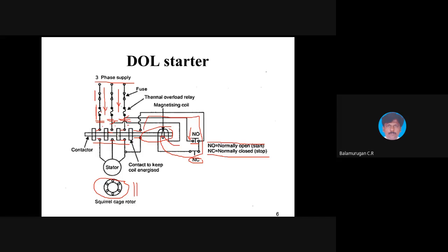And here you have to remember the condition. We are not reducing any voltage here; we are applying the full voltage. So these two currents will be almost the same, and we will not have any ratio. So the starting current will be equal to the short circuit current. This is the final equation for the DOL starter, the ratio between the starting torque and full load torque.